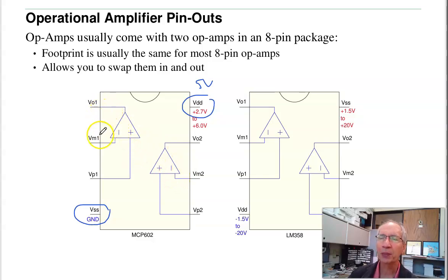They put the plus and minus, or the output and minus, close to each other because a very common op amp to use is a voltage follower. Short these 2 pins, and if I apply a sine wave in, I should have a sine wave out. That's a buffer.